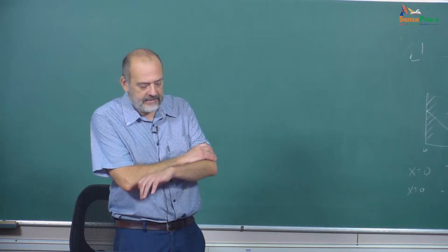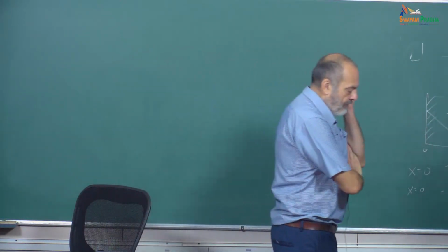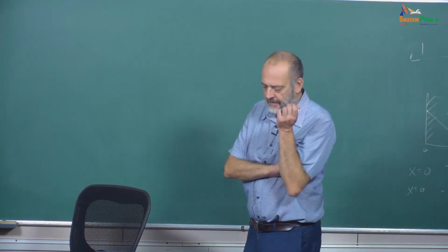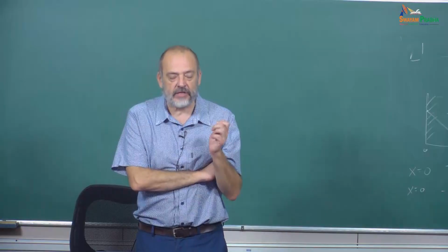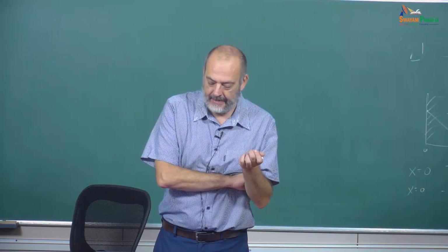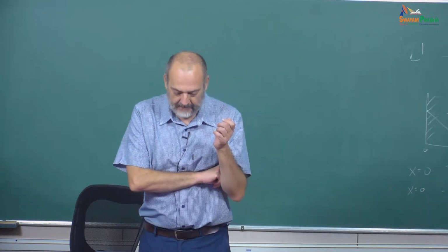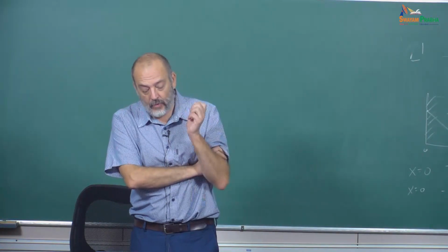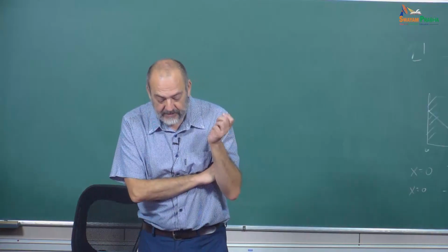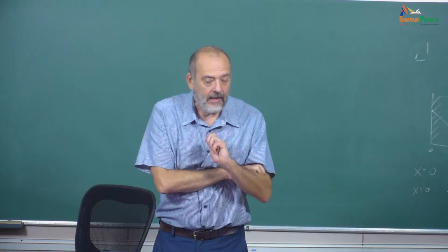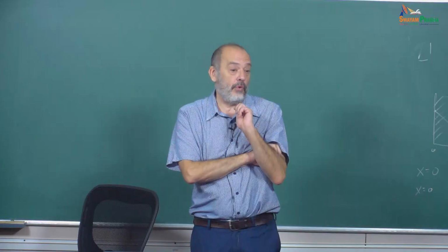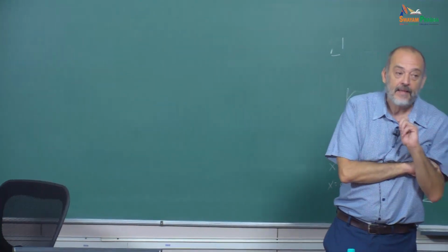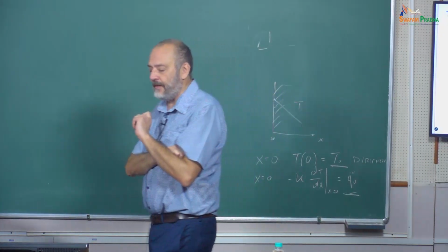And in this case, instead of the equation for the shear stresses, tau equals minus the dynamic viscosity multiplied by the derivative of the velocity in space, we have here the heat flux. And so we can write an expression that is finally defining what we have in the Newton law. In the Newton law, we have this h, but nobody knows exactly what it is. Now we have a little bit more information.